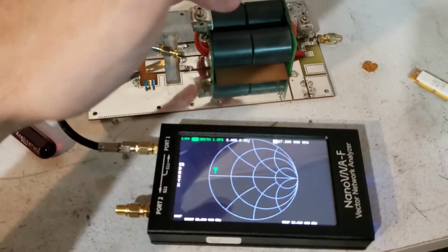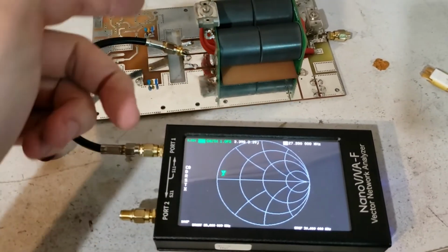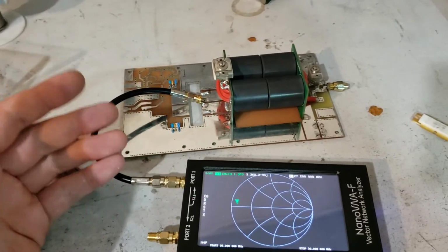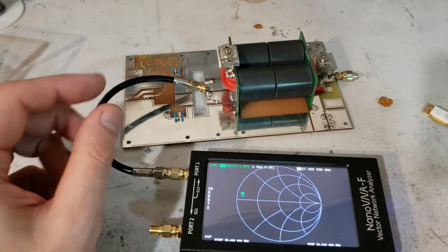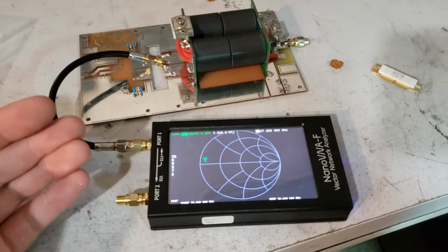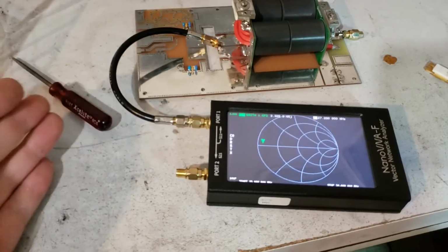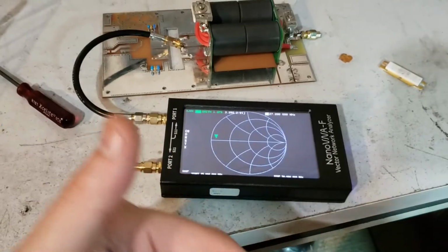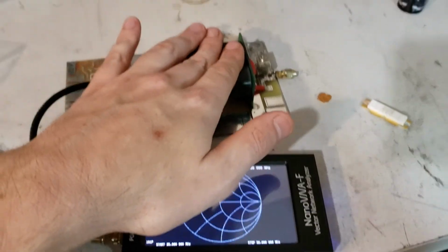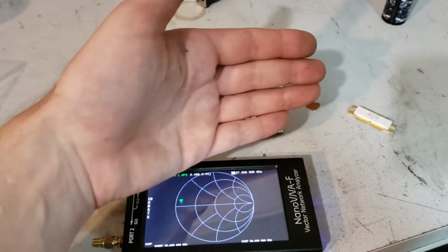So if you were tuning an amplifier for the first time, you'd want to pre-tune it to an approximate value, plug in your transistors, fire it up, and slowly start to increase the power, and see what your harmonics look like, see what your power gain looks like, your input power versus your output power, and then you might want to tune these capacitors on the output transformer to get the maximum forward power, the maximum gain.